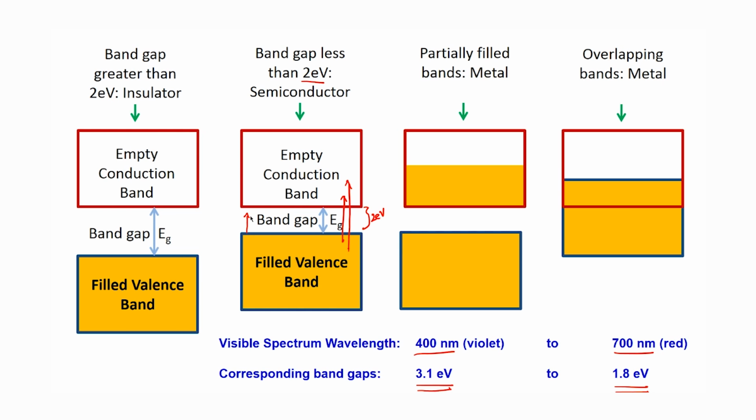Okay. So, generally speaking, they are transparent to radiation of wavelengths less than the band gap, and therefore, interestingly, normally you think that some low energy thing will get absorbed, high energy thing will be able to pass through, that is the intuitive way we think of things. Here it is the other way around, the high energy photon gets absorbed because it is able to cross the band gap, but the low energy photon is unable to cross the band gap. So, it just passes through the material without doing any transition. So the material sort of is transparent to this radiation.